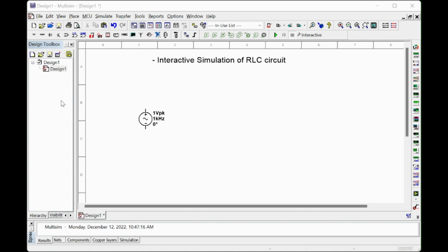Let's pick a small value of the resistor. Let's take this one, 270 ohm. By the way, I'm picking these components randomly. There is no logic behind how we are going to collect them. I'm just making you learn how AC interactive simulation can be accomplished within Multisim. Finally, now we need a capacitor. Let's select a bigger value to see greater voltages appearing across the capacitor.